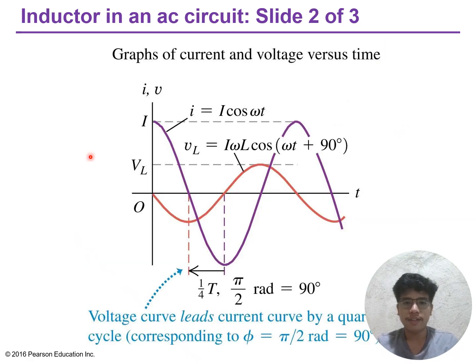So moving on, a diagram for an inductor in an AC circuit with a voltage and current phasor separated by 90 degrees, demonstrating the leading voltage-lagging current relationship. The phasor diagram presented here reveals the distinctive phase relationship for an inductor.